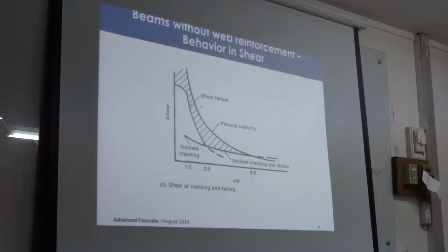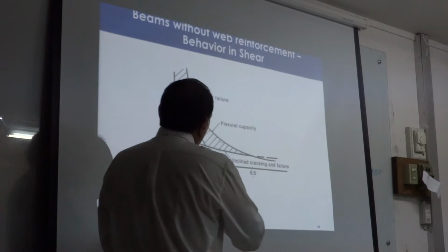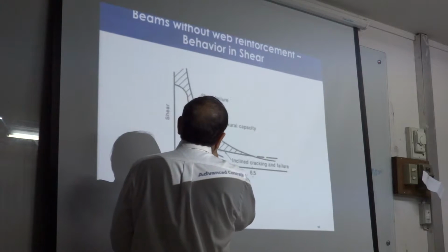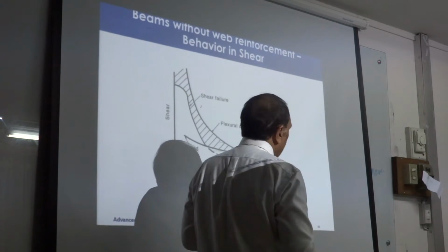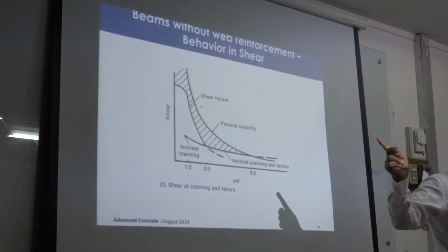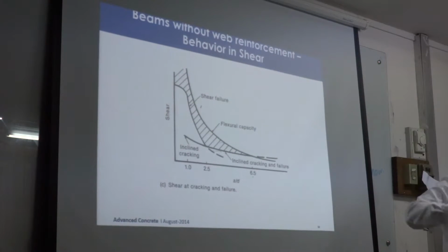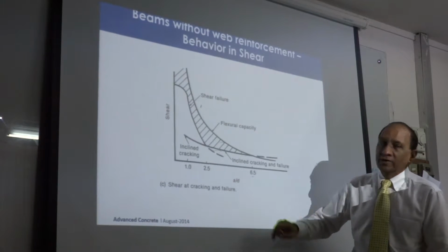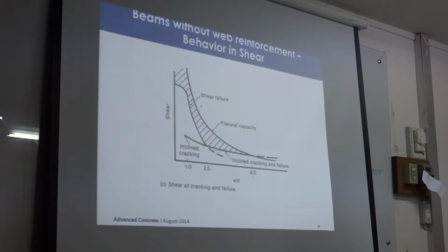This is just more details on how the concrete shear capacity and flexure capacity and shear failure, they interact with each other. Again, most of it coming from the Mohr circle and also compression field theory and other theories. So they're trying to tell you this is a very important parameter, A over D. A means shear span or length, where the shear is active, and D is the depth, and that controls the shear behavior because that controls the B and D region.